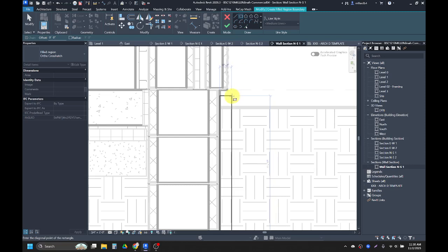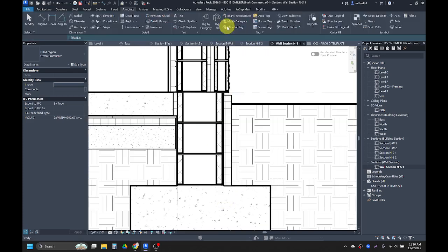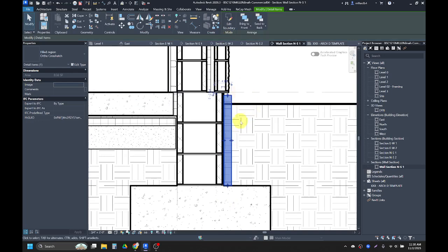I'm going to make it 2 inches wide. How tall am I going to make it? About that tall. I want to leave a little bit of space between where my split seam U is and where this part ends. I'm not necessarily measuring it, but I want it 2 inches wide, and I'll hit my green check. And I'll split it in half later.